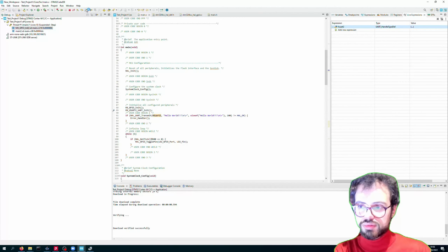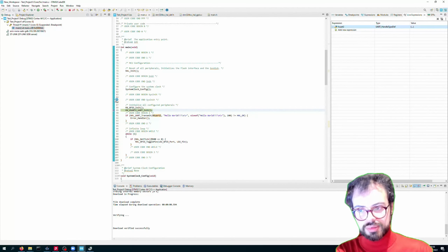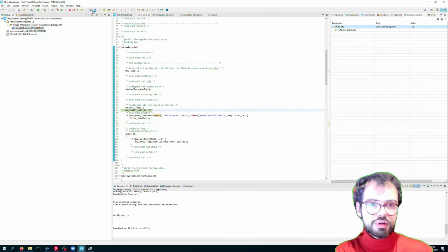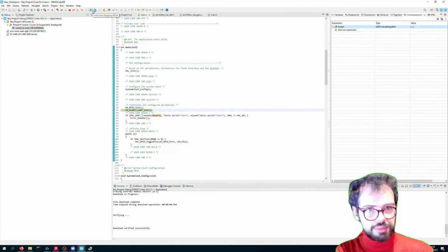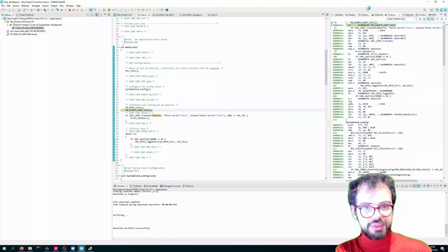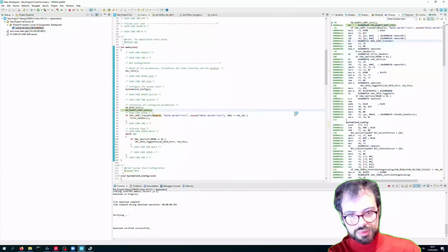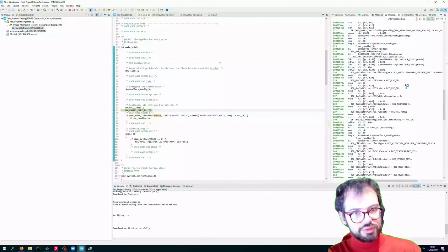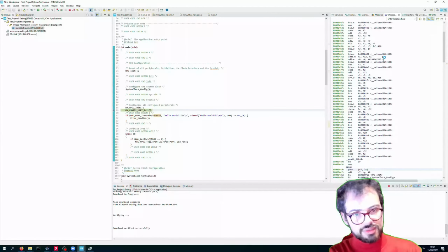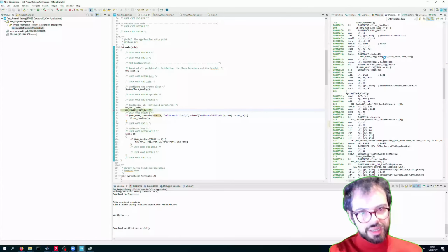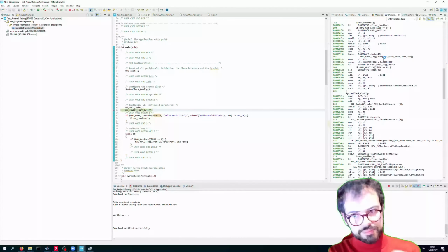If I wanted to go step out, step return, I'm outside of the Gpio initialization. If I want to go even more deep, I can do an instruction stepping mode, and basically it will open the disassembly and it will show you everything, all the machine code that corresponds to what you're doing. So eventually you are also able to modify this code if you can identify again the most critical tasks. You might be able to do hand optimization that will save you some time.